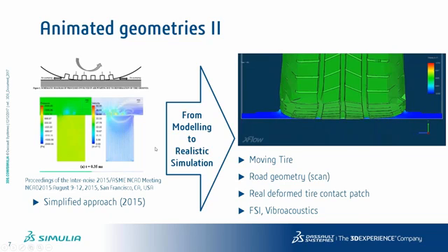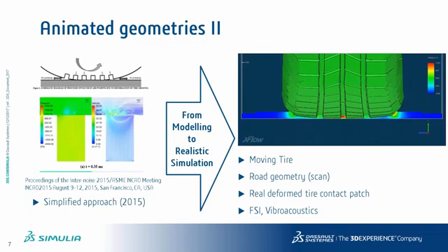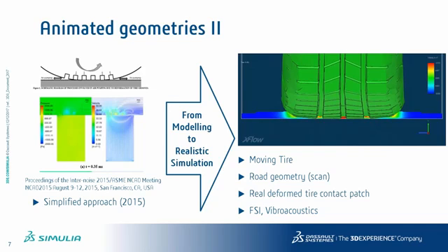We now try to go even into more detail, so we can actually simulate the reality of how the tire deforms. So in that case, you can have a simulation in Abaqus, for example, for your tire deformation, export all this sequence of geometries, and then use that as a driver into the XFlow fluid simulation.